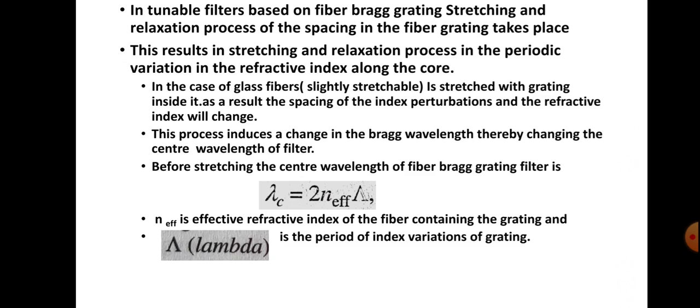When we stretch that, the spacing between the grating structure changes. As a result, the corresponding wavelength selection will be changed. Suppose we are using glass fibers, which are slightly stretchable. If we stretch it, there will be a stretching of the grating inside that fiber.